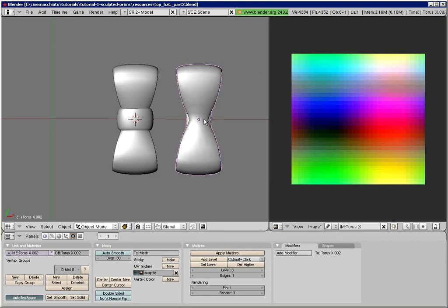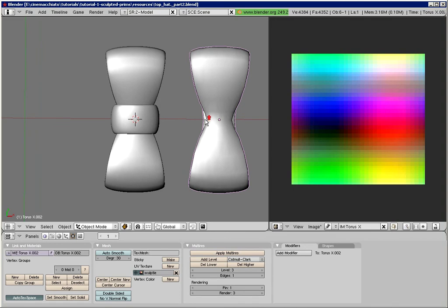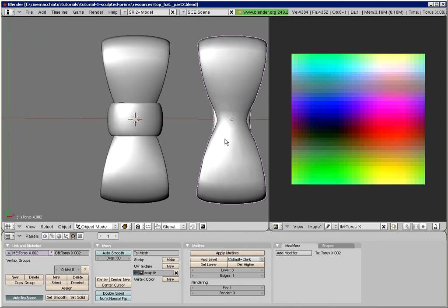There is another very important issue here, which you must know about. The Set Solid and Set Smooth buttons define two different lighting models. And this setting directly influences the way textures are baked. For the moment, let us say that the Set Smooth option will make the sculpty look very much similar to how it would be seen in Second Life. And let us keep with this mode for now. I will get back to this in the next tutorial.